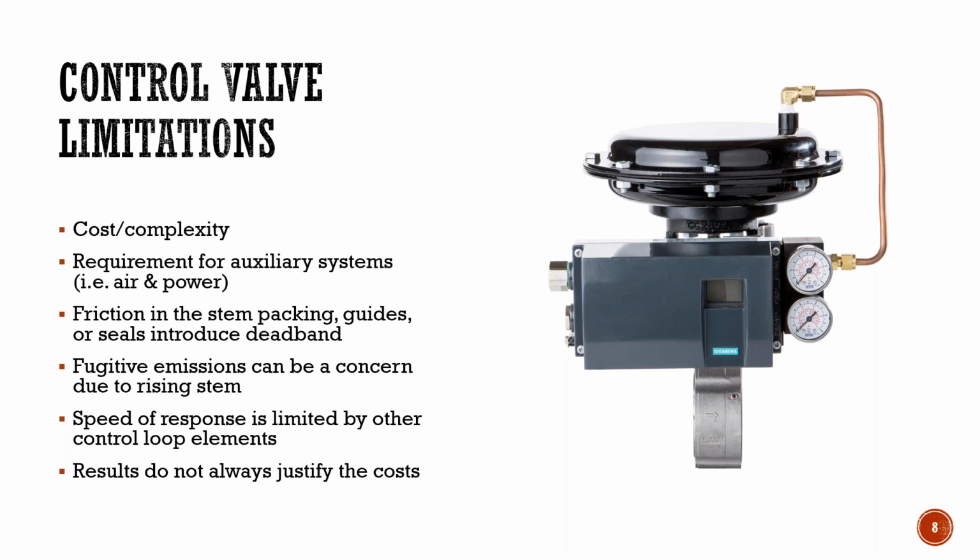So those are additional considerations. Friction in the stem packing, guides or seals introduces deadband. Emissions can be a concern due to the rising stem. So with a nasty medium, potentially you could drag emissions up through the packing and they could escape to atmosphere.